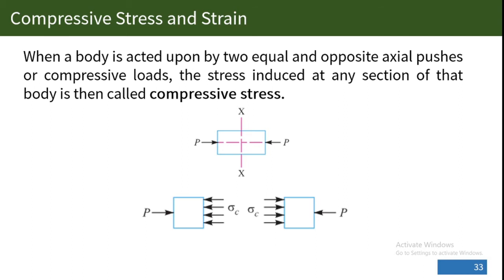Looking back at the first type of stress, which is the tensile stress, the two forces, equal and opposite, are applied from the center of the body outward.